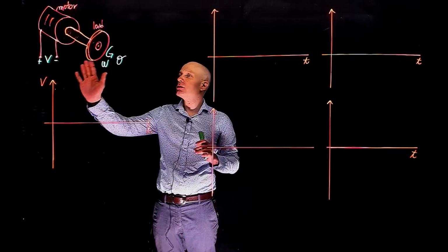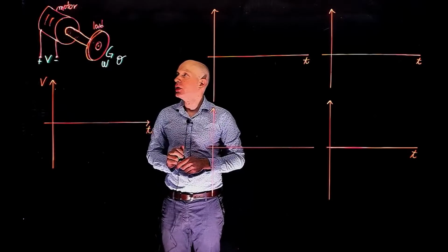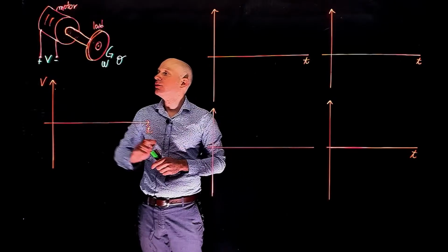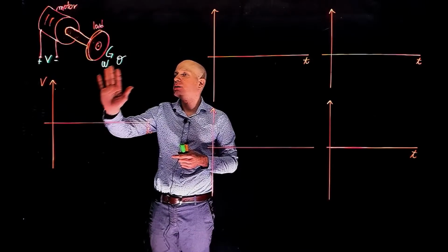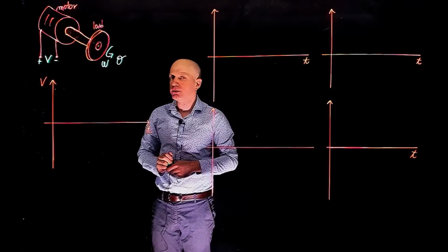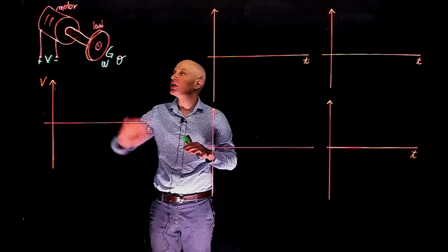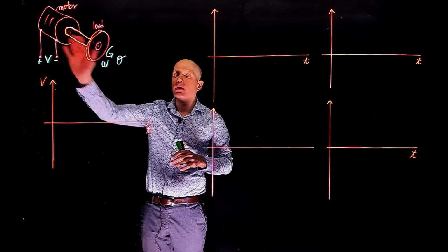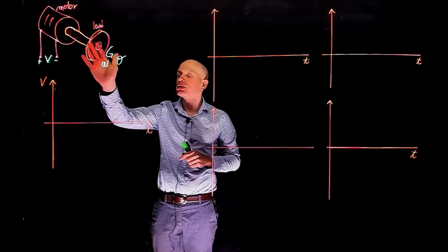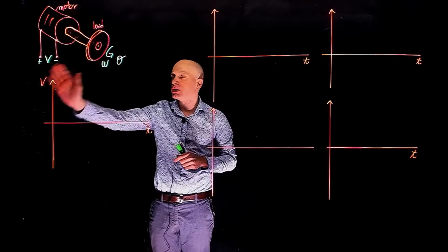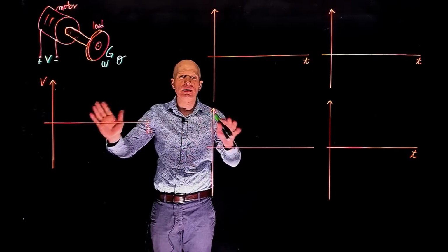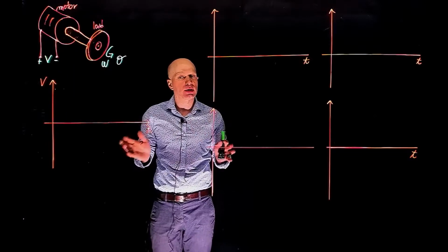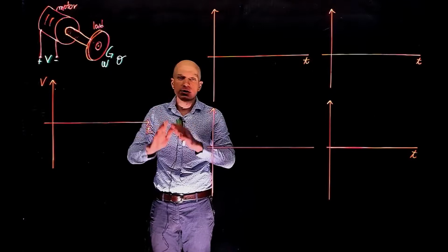We have a DC motor that drives an inertial load. The DC motor takes an input V, which is a voltage, and the output here will be either the speed or the position of the output shaft. For simplicity, we are going to neglect all the electrical properties of the motor. We are assuming that a voltage gives a torque to the load, and that relation doesn't have any delay or any transfer function between them. It's simply a gain. Of course, we know that that assumption doesn't hold true, but this is just for simplicity here.